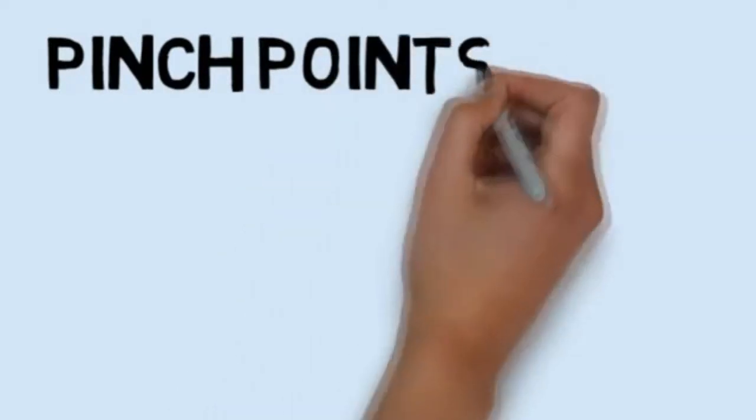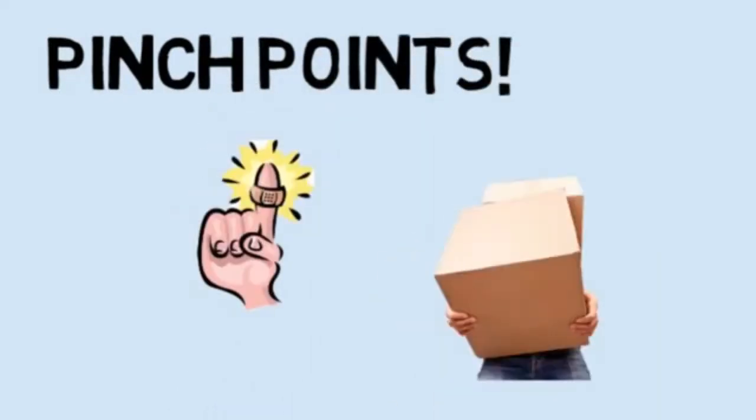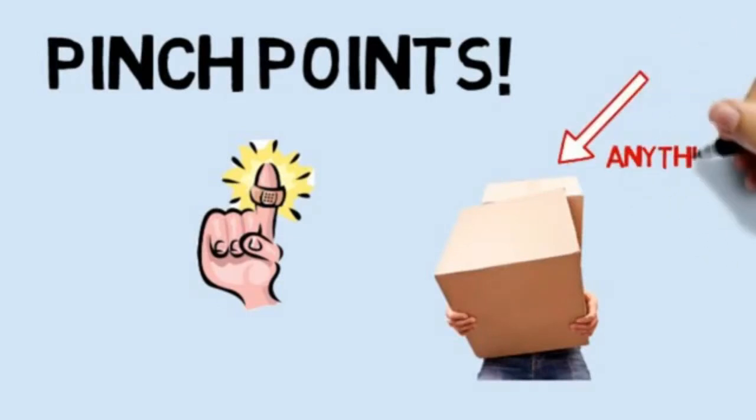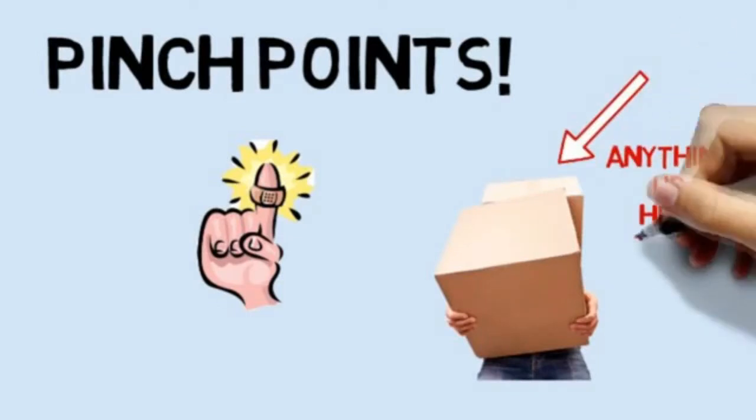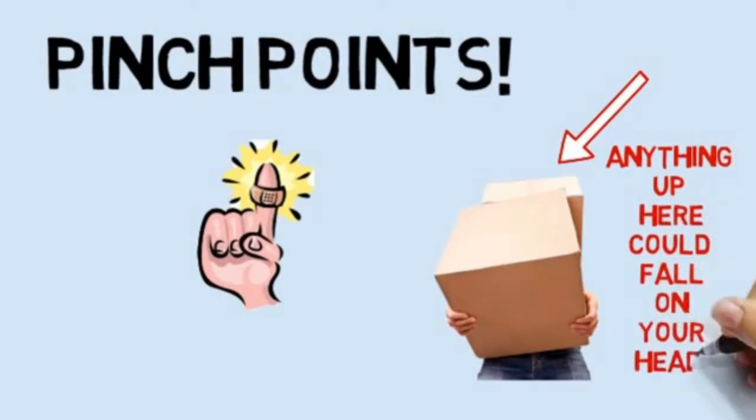If it's back on a shelf, slide it out to get it closer. If it is coming out of a tight area, make sure you have adequate room for your hands and arms. Watch out for pinch points. Be aware of any adjacent obstructions, and always make sure you can see the top before moving.